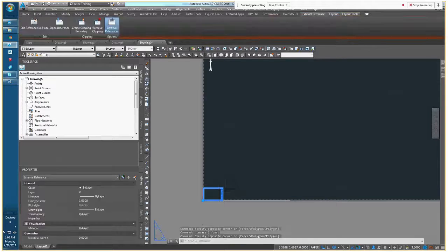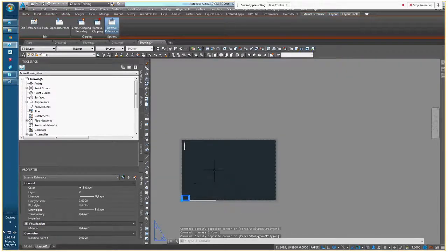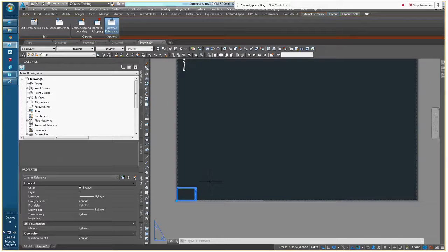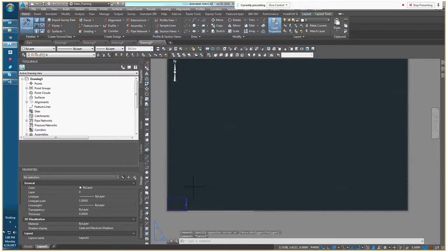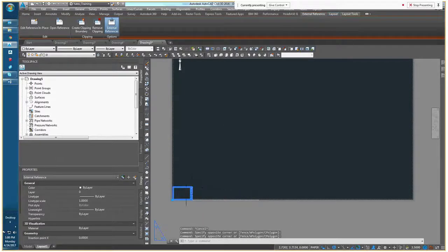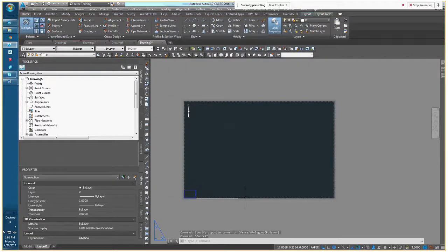So we brought in that exact same title block, but into a different template. A template where feet are set as the native units as opposed to unitless or inches. Okay? Our detailed DWG is set up to be unitless, whereas our Civil 3D template is always set to feet. So, because of that units discrepancy, this block came in at exactly 1/12 of its normal size. This paper space is set up to be 22 by 34.